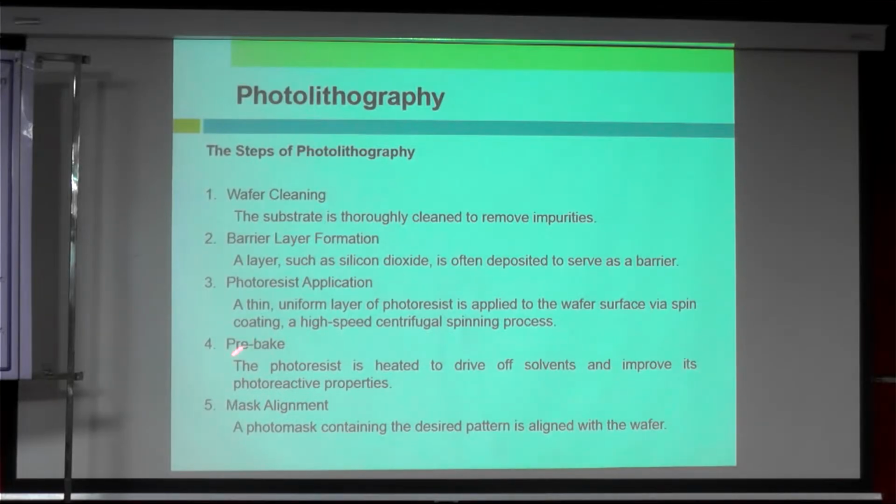That is a pre-bake process. Then go through the mask alignment. The photo mask containing the desired pattern is aligned with the wafer. So alignment is important, though the first process might not be that critical.